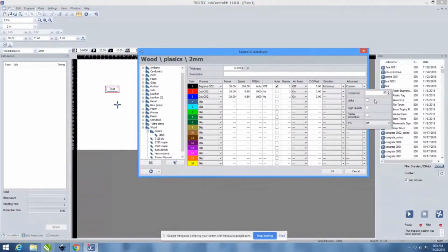John, did you want to explain some of these? Basically, the main one to be concerned with is correction for the purposes of cutting. This is probably the most difficult thing to explain, but when the laser goes to make a sharp corner, for instance if you're cutting a triangle, the laser has to lower the laser power as it physically lowers the speed to make the corner.